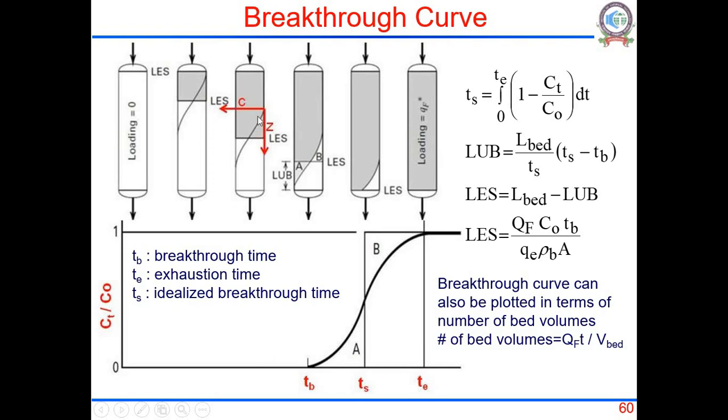So this would be an adsorption zone. We can hypothetically think that this would be the adsorption front, but actually there is an adsorption zone. Some books call it the mass transfer zone. This is the zone where mass transfer is occurring from the solution phase into the resin phase. And as we put more and more solution, this adsorption front is progressively moving down.